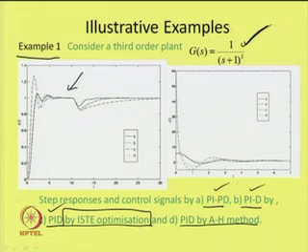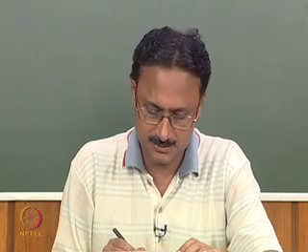The control signal given by different methods are also shown over here, and the plot shows that the PIPD controller gives us improved control variations. So, less control effort is employed to obtain superior performance compared to other controllers. This is the benefit one gets from the PIPD controllers.